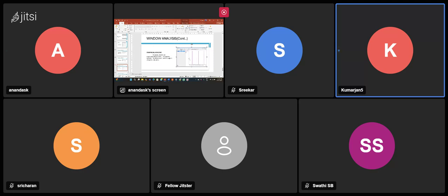There is communication between the EVCU and the brake control module, and you can see that communication with the help of the graph. If it is failing and not accepting because of some error frame the EVCU is sending, then you can go to the EVCU code and modify it. So with the help of the graph window we will know exactly where it is failing and how it is passing.